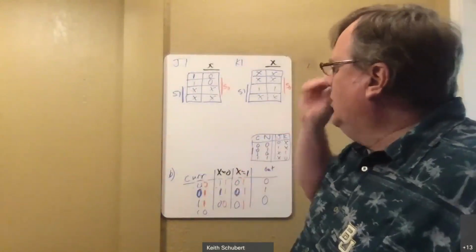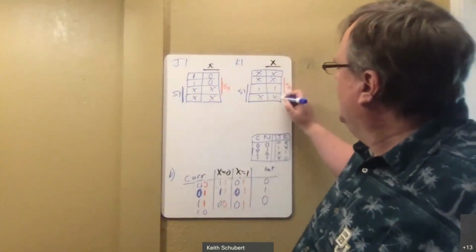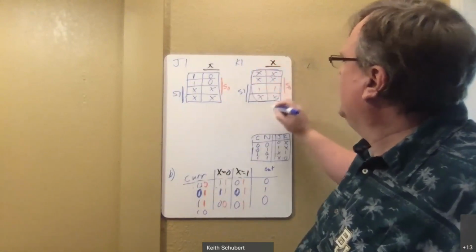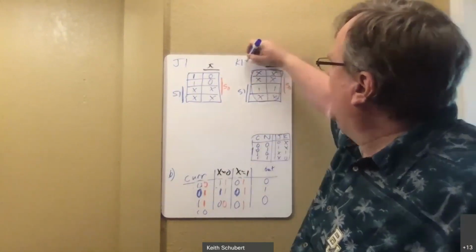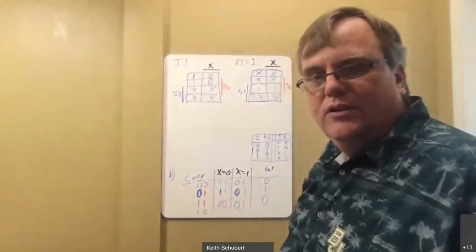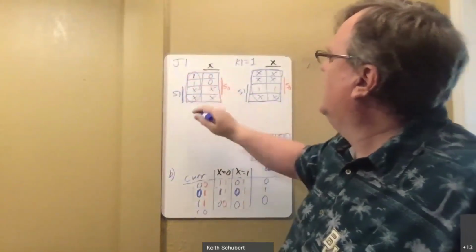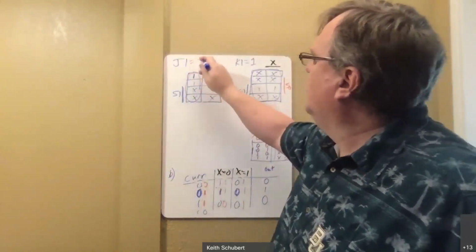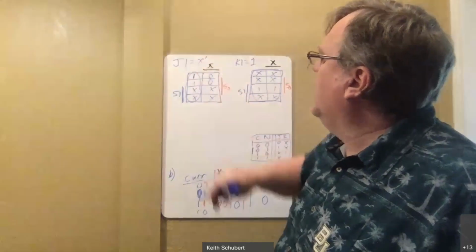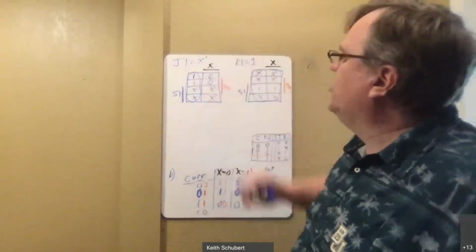All right. But in this case, I'm being lazy. And this gives me a really easy encirclement for the K here, which is just everything. So that means my equation is K1 is equal to 1. It's always true. And when I do my encirclement for J1, it is equal to X. So that gives me a really nice, simple implementation. Do we feel good about J and K?